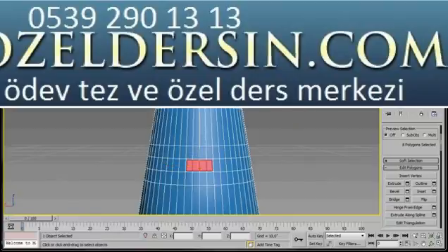Now we can scale it down. We'll select the scale tool, and we're going to scale it down only on the Z axis. If you look down at the bottom panel here in Z, we'll scale it down to 60. So I'm just going to slowly drag it down. Notice in the Z, when it says 60, we can let it go. There. Now we're going to delete them.